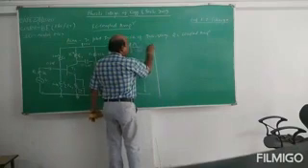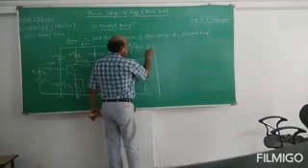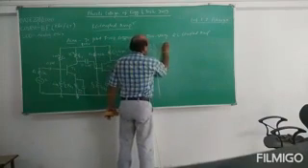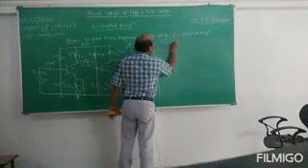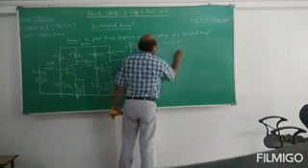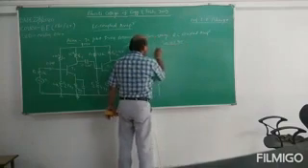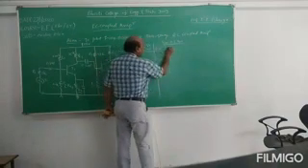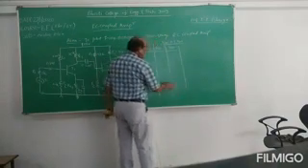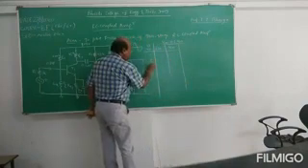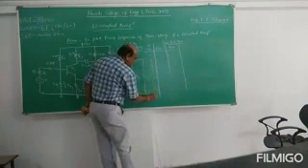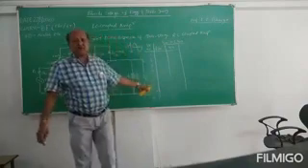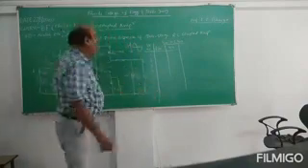Put the serial number in the first column, then keep V in equal to 0.5 volt peak to peak, and for this V in we change the frequency F in and measure the output voltage. Take 1, 2, 3, 4, 5 and so on, around 12 to 15 readings.